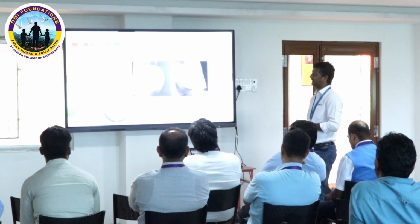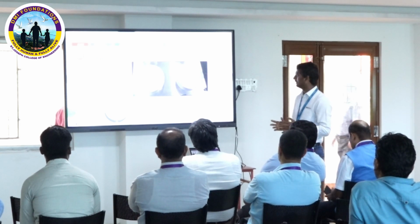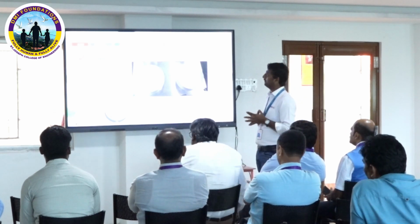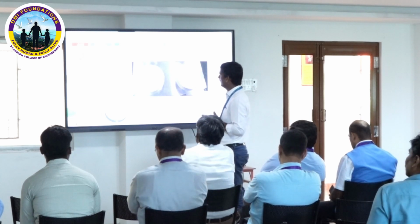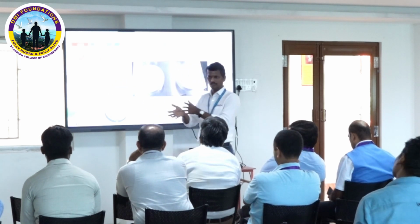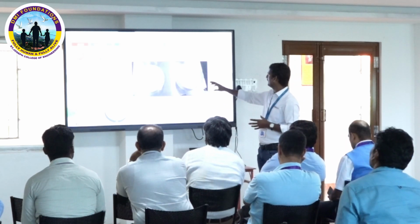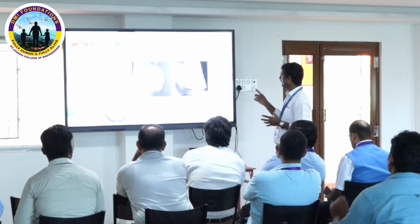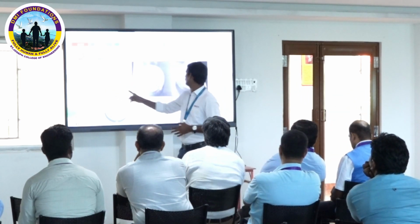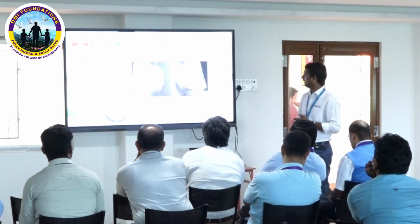And there is a dialysis filter. This is currently under testing only. They are trying it out and are about to receive the result. In this case, the material is SS316L, and they wanted all these channels in one single component. You can see the channel is around 4.2 mm, and it has a length of around 94 mm. So this 94 mm length with a 4.2 mm channel is a very difficult thing to obtain. That's what they tried to get done.